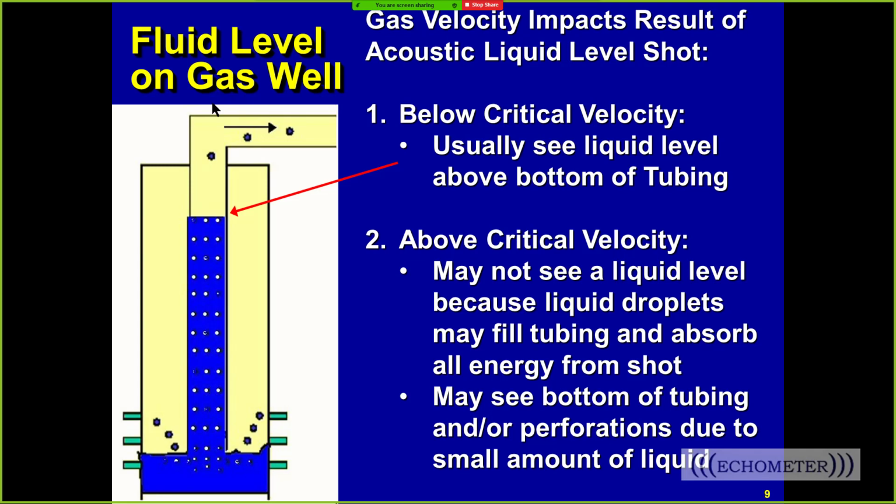And then as you keep the well closed in, the gas and the mist will separate gradually, and the dry gas will collect on the top, and the mist will stay on the bottom, and it'll stay a mist as you gradually build pressure and push the mist level down. So that's what you'll see. And if your well has no liquid, which is very uncommon, and you're flowing above critical rate, you might just see the end of the formation, or you might see the bottom perf. But anyway, that's what you'll see.